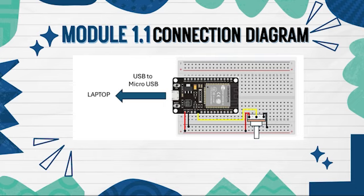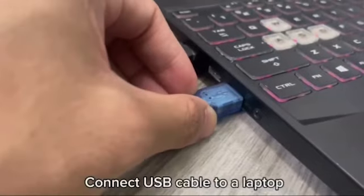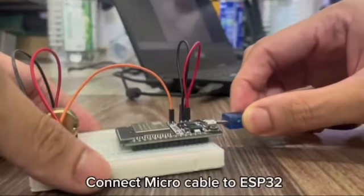First, prepare all the components. We need ESP32, micro USB cable, potentiometer, breadboard, and jumpers. This is the connection diagram. Connect the component based on the diagram. Connect USB cable to a laptop. Connect micro cable to ESP32.